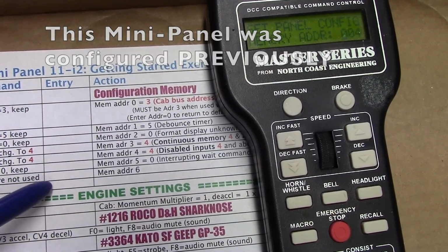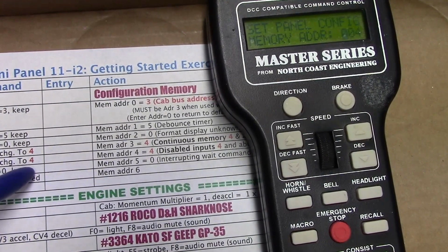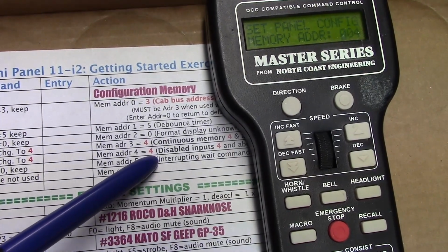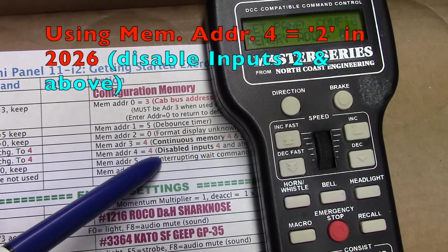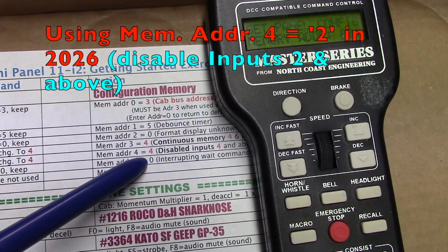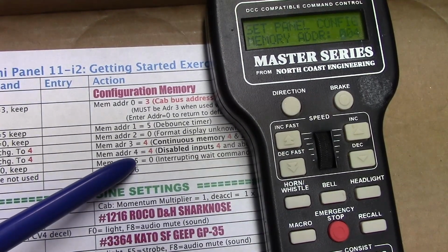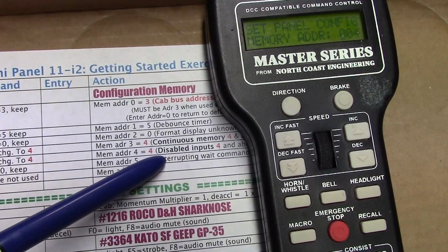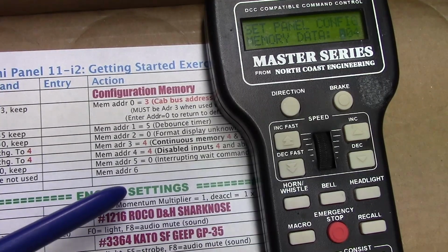Now we'll push the enter key again, memory address 4, here's the one for the disabled inputs, that's set to 4 also, and again, we'll leave it that way. But if we wanted to disable inputs, say 5 and above, we'd put in a 5, or if we wanted to disable inputs 2 and above, like we've done for some of the latest videos, we put in a 2. So we'll just push enter to leave it the same way.